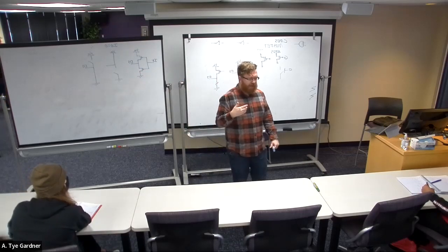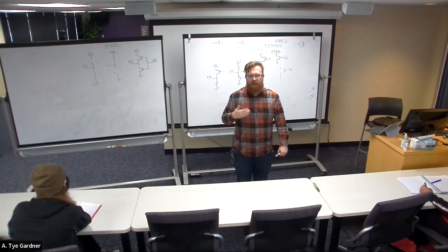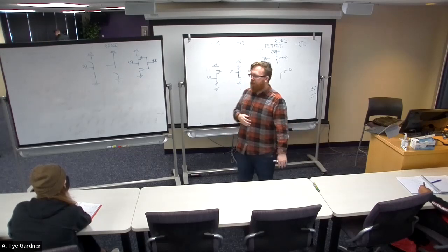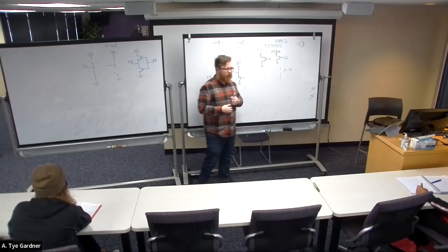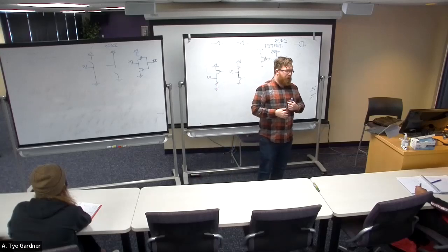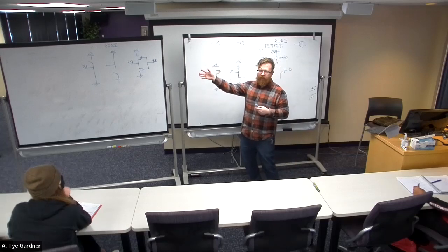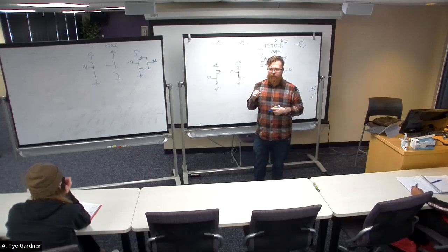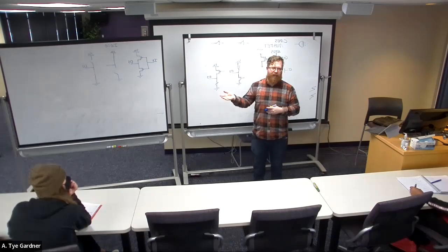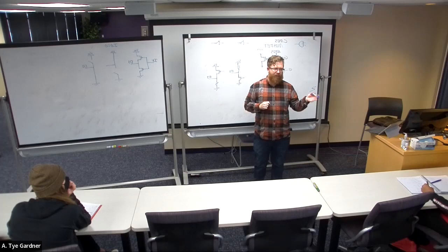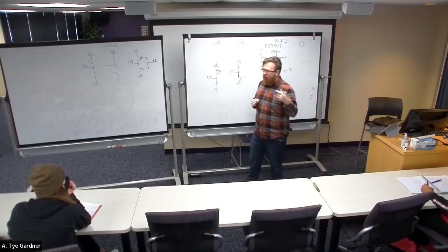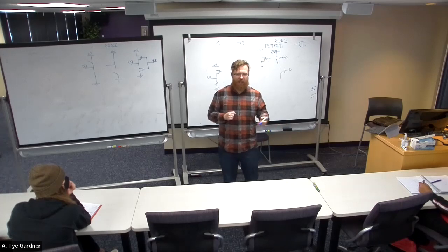But one of the issues ends up just being the manufacturability of it. And the other problem is from the designer standpoint: these guys get hard to work with when they start getting small. So I've done a lot of design in these guys in an old technology that we call 180 nanometers, because the minimum feature size that you could make in that process was 180 nanometers. So 1 meter times 10 to the negative 9th times 180. So very, very small. Advanced technologies that are going into products are getting down to 14 nanometers, 12 nanometers, 7 nanometers.